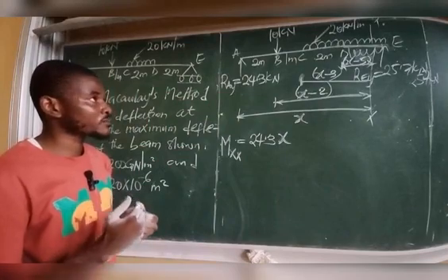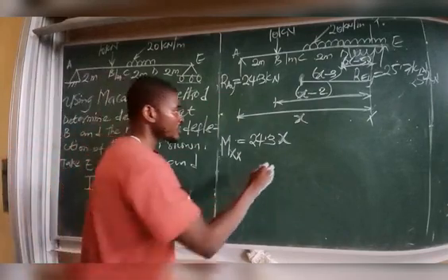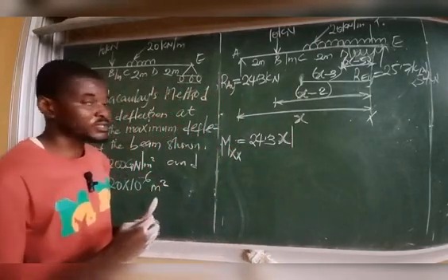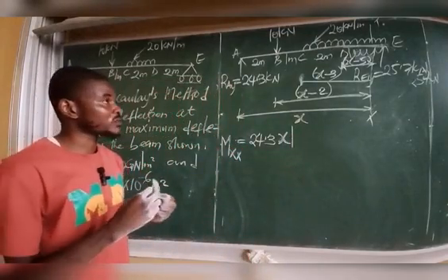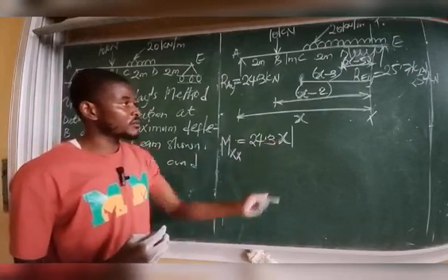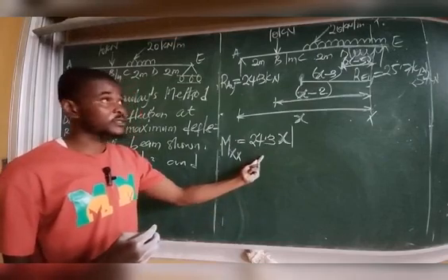Now, after the very first moment, Macaulay says introduce a Macaulay bracket. So I simply bring down a bar. This bar is what a Macaulay bracket is, a bar to separate each of the moments from one another. So I introduce the bracket after the first moment.